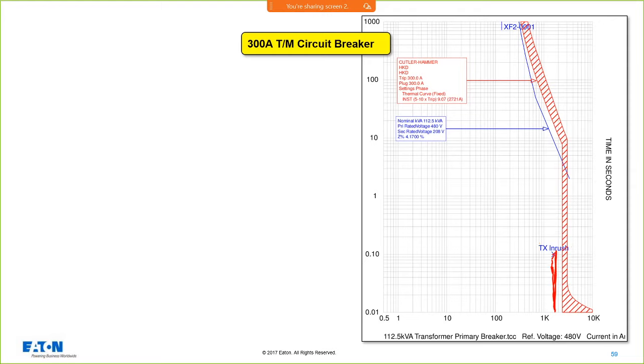So if I size this per the National Electrical Code, you would say I have a concern in overloads in this region, which after we select the secondary breaker, my argument would be you're protected from overloads due to the secondary overcurrent protective device. But for short circuits, you're going to clear that fault fast on instantaneous. Now that's a standard thermomagnetic breaker.